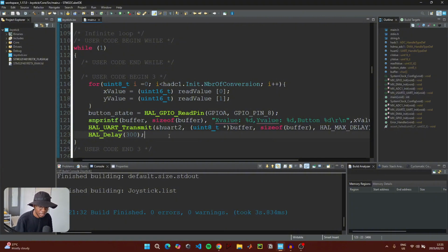And then when it comes to the circuit connections, they are very straightforward. You just need to connect the ground on the joystick module to ground on your microcontroller, and then connect the VCC pin to 3.3 volts on your microcontroller. It's very important to use 3.3 volts instead of 5 volts so that there can be a clear distinction between when you move to the lower X or Y values and to the higher X or Y values. If you use a larger voltage, you won't have a decent range.